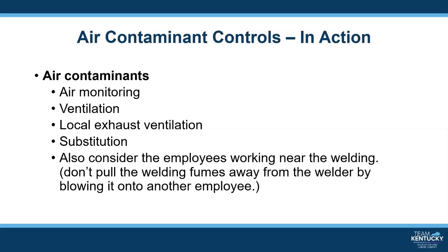As I had mentioned earlier, you could use substitution of the hazardous product with a less hazardous product. You could also use substitution for a less hazardous welding machine process or other process used for melting the metal. When the methods I've discussed are not effective or not feasible, then respirators could be provided to the employees when needed.